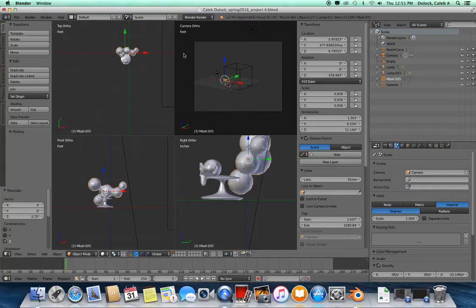Alright. Our next step in our project process is to determine how many polygons or triangles our model is made of. Augment is sensitive to the number of triangles that an entire model can be made of, or an entire scene. It does say in Augment that you can upload up to 1 million triangles, but the truth is that most models uploaded at that size don't operate very effectively on a mobile device. So my recommendation to keep it even and to even out the playing field so that anyone can open your model is to keep your model pretty low on the triangle count.